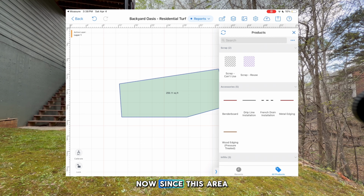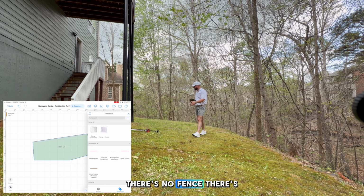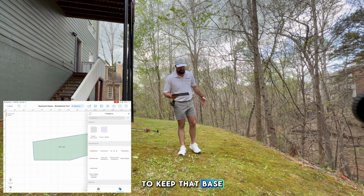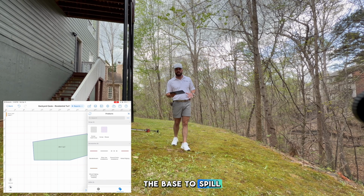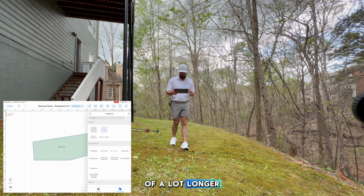Now, since this area, there's no hard concrete it's meeting up against, there's no fence, there's no pavers, it's all open. So we're going to need to keep that base tucked in. And there are other videos on product knowledge that essentially explain why that's necessary, but we don't want the base to spill out of the turf, what's underneath the turf. Keep it tucked in, it'll last a hell of a lot longer.